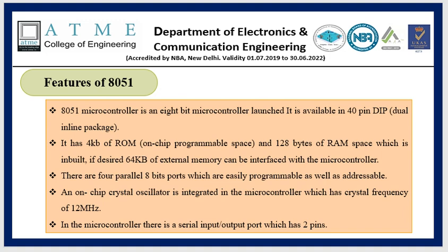There are 4 parallel 8-bit ports which are easily programmable as well as addressable. The microcontroller has an on-chip crystal oscillator, integrated in the microcontroller, with a crystal frequency of 12 megahertz.